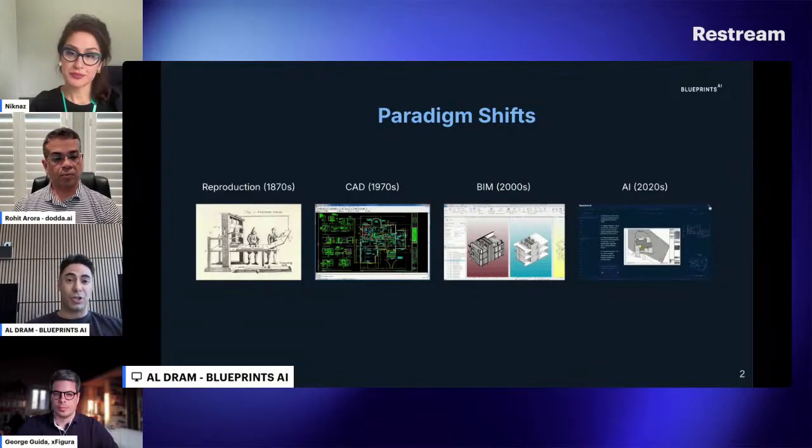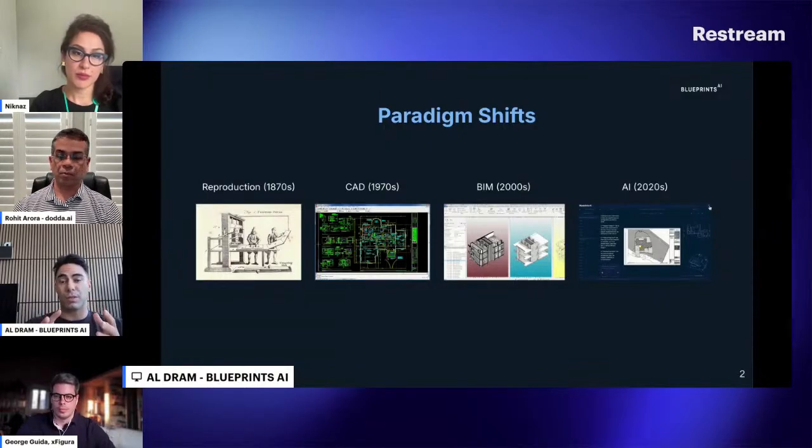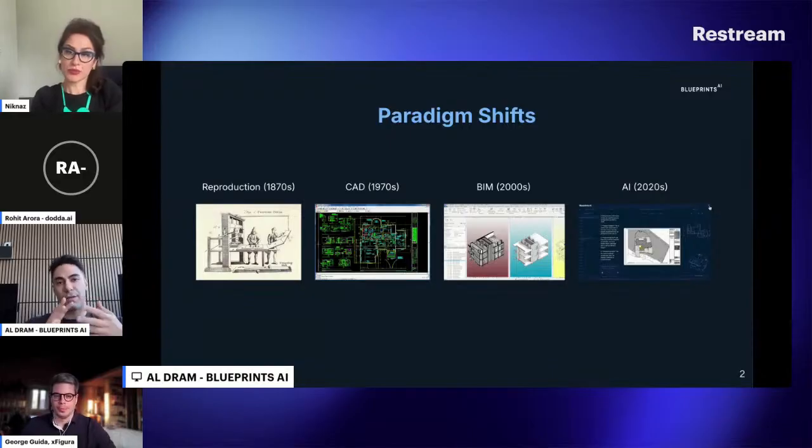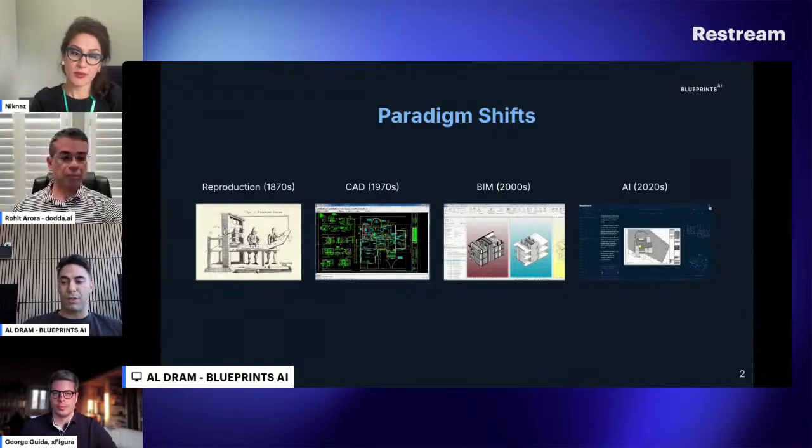And the next shift was when BIM was introduced, and the nice thing about BIM is that when you change something, if you set it up well, the revision is going to be on the whole building information. It's going to change the takeoff, the number of doors you need to buy on the table. And the floor plan and the elevation and section, everything changes together. So revision gets easier.